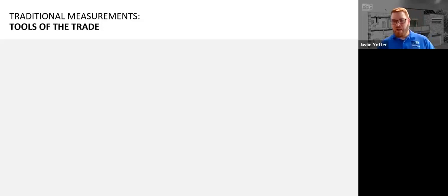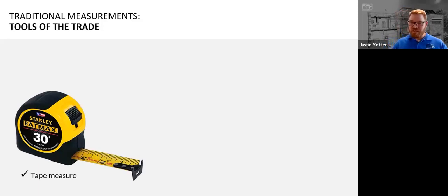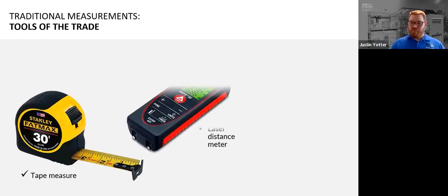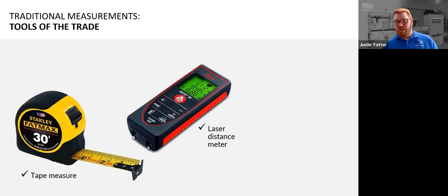You can use a tape measure to measure lengths, obviously, of anything. And for heights, you can measure all the risers and the stairs, drop it down a balcony, run it up a wall, etc. A laser distance meter, or disto, can perform trigonometric functions instantly and get you lengths and heights in all sorts of ways. Some come equipped with a camera feature as well, which really helps with long shots.